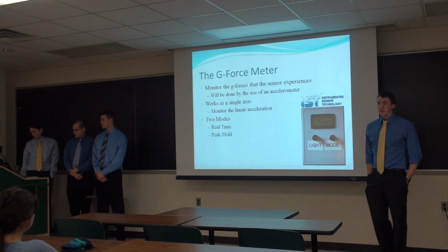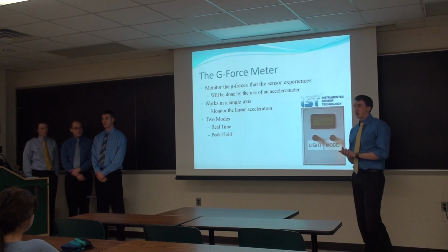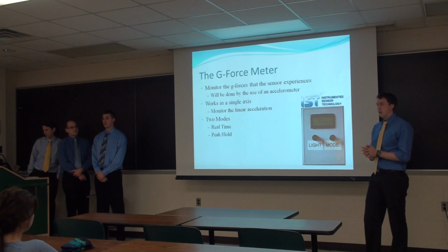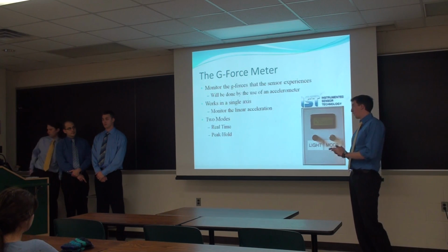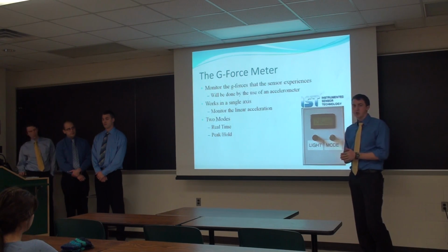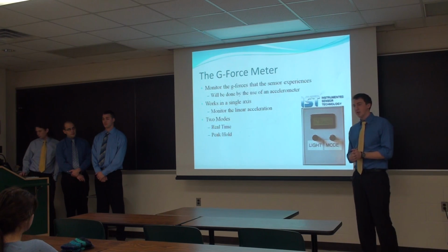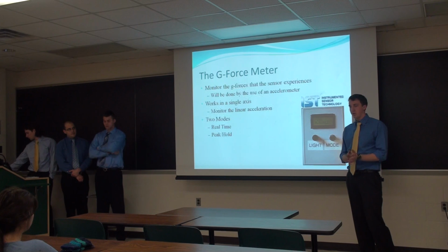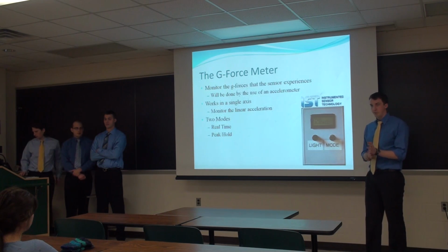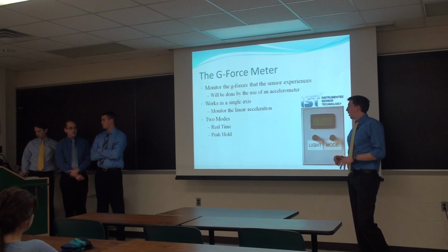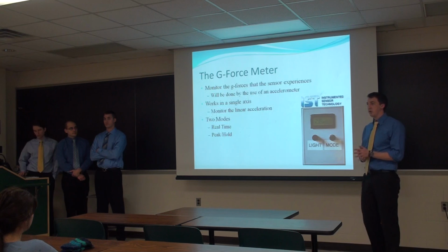So basically what we're going to be doing is developing a device that will monitor the acceleration experienced by that device. We're going to be doing that by the use of an accelerometer. Based on what our sponsor told us, he wants it to work in a single axis. Most accelerometers nowadays work in 3-axis, so they work in the X, Y, and Z coordinates. Ours will just work in the X coordinate. In addition, we'll have 2 modes, real-time mode and a peak hold mode.